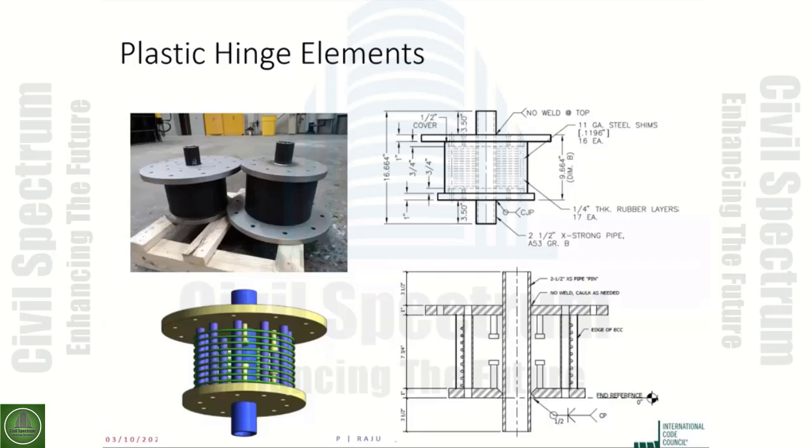Moving to the lower part of the slide, there's a different version where we use ECC, engineered cementitious composite, that can minimize the damage. Still cementitious material, but has a much higher resistance to damage because of its higher tensile strength. So the detail for this one would be what you see on the right side here. So it has some similarity to conventional concrete.